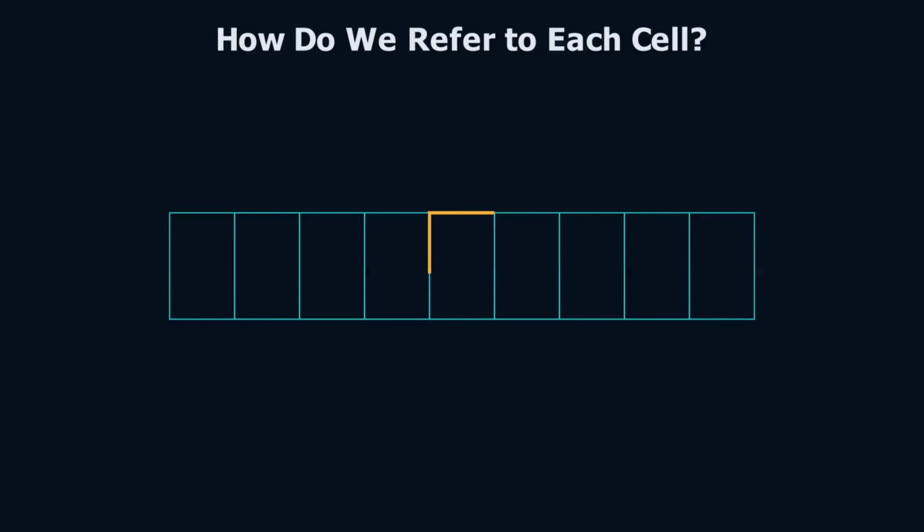Suppose we are solving this particular cell. We call it the present cell, or simply P. Its neighbor on the left is called the west cell. Its neighbor on the right is called the east cell. During every calculation, information moves between neighboring cells. Instead of writing long descriptions, we simply use symbols like U sub P, U sub W, and U sub E. This simple notation will appear throughout the rest of our CFD solver.